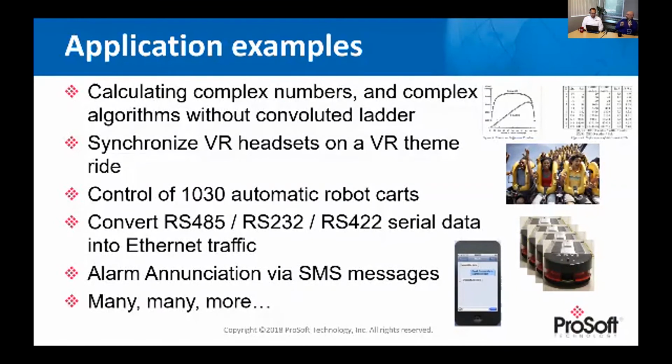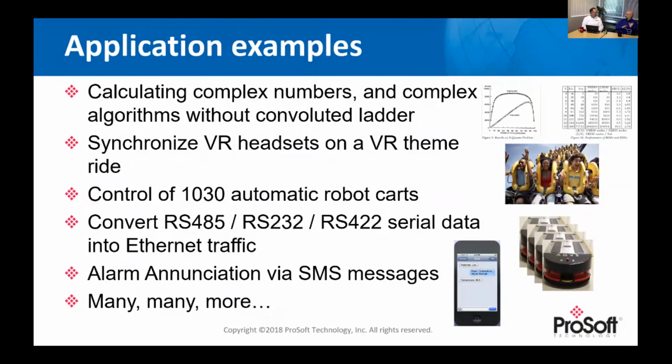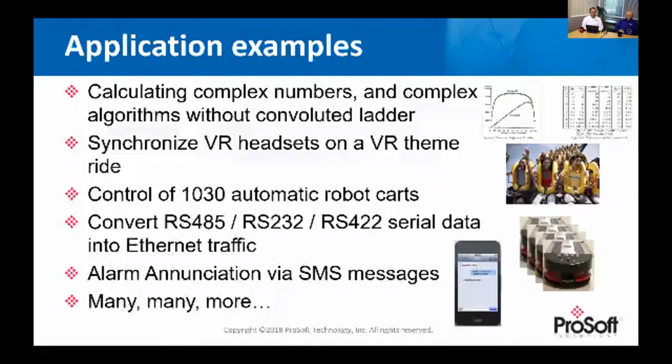They could start the machine from that same interface, tell it to produce one of these, and they could verify it as it comes out, make sure all the parts are there. But the other advantage they had was that they had these existing recipes stored in the module, and they could just pull one up when they need it and then feed it into the PLC, which of course then controlled all of the machines, or the parts of the machine, I should say.